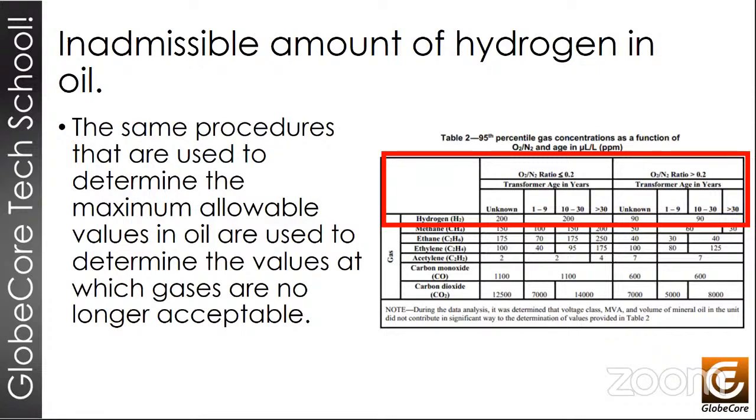Now, if we recall the previous table, we will see that there is a range of values that are considered to be warning ranges, because if the hydrogen value exceeds the values from the previous table, but does not exceed the values in this table, we can determine that the transformer is in a questionable state, and then it means that we need to conduct a deeper investigation into the possible fault or malfunction, where we can also take into account the values from other tests that we can and probably should perform, which is of great interest and will be very good for determining the exact possible fault and identifying the subsequent repair and reclamation process.